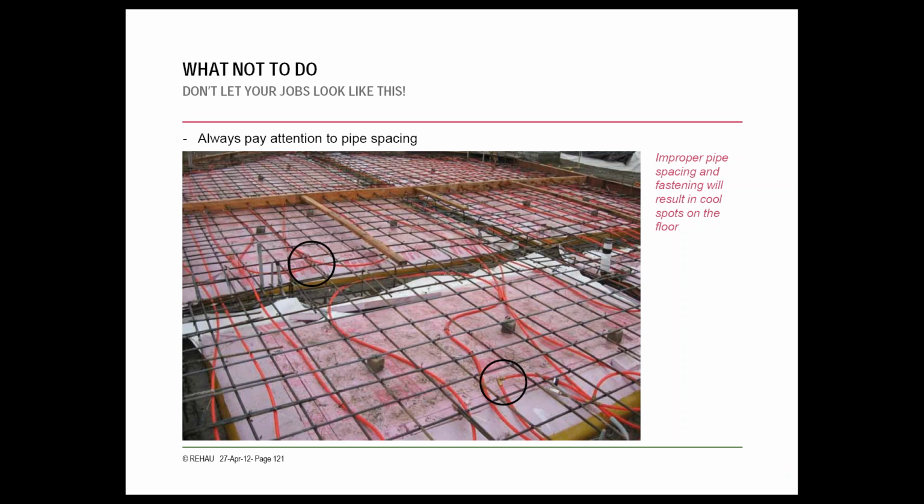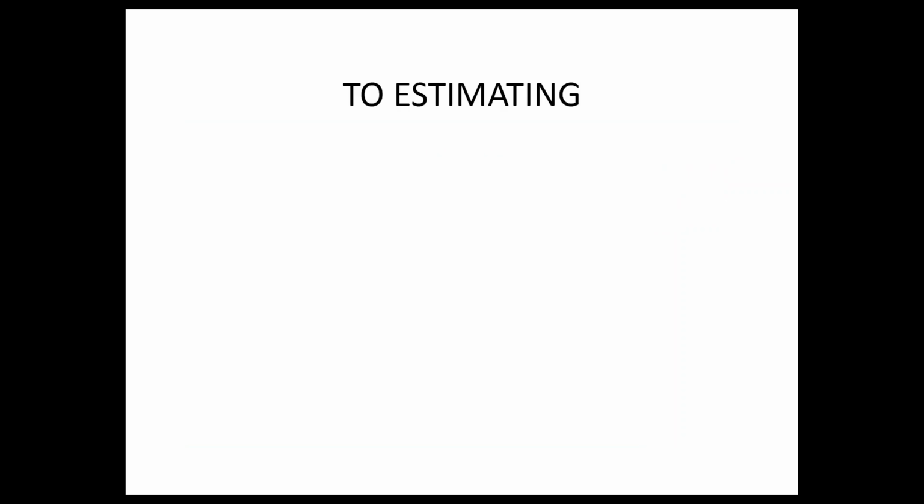Also, you ideally want to avoid connections within the slab, just because they could create a point of failure. As I mentioned, there are certain PEX fittings that are approved for concrete slabs. So if you have to use one of those, but even in that case, only where necessary. Avoid it if possible.